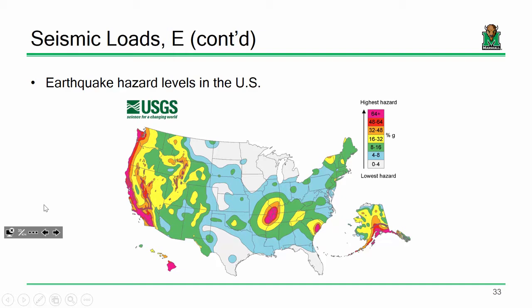if an earthquake were to occur. I mean, if you look here, this seismic hazard level, this is Western Kentucky, right? And this is just as large of a seismic hazard level as out in LA, okay? So if you're designing a building out in that region, you've got to design it just the same as you would out in LA. A lot of people don't realize that, but it's all about risk, okay? If that region were to go because it lies along a fault line, it would be bad, okay? So we have to address that accordingly. Does that sound good? All right.